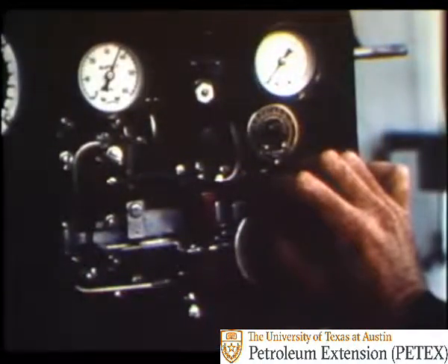Pressure controller adjustment of the set pressure is done in a similar manner. To raise the pressure, turn the knob in the direction of the arrow. To lower the pressure, turn in the opposite direction. These adjustments must be made gradually. This is the basic controller function, that is, to control the liquid level or pressure.